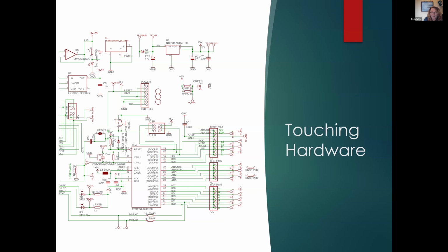and all the extraneous components, it's like a block diagram, like a system or a software block diagram with lots of extra squiggly lines. In general, the bigger the component is on the schematic, the more likely it will be important to the software. So if you have to puzzle out a schematic on your own, start with the big boxes. Google the numbers in and around those components.